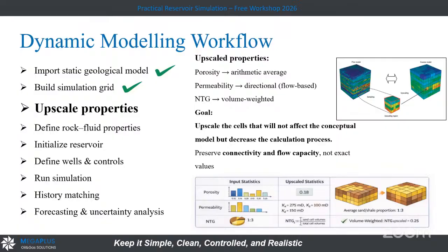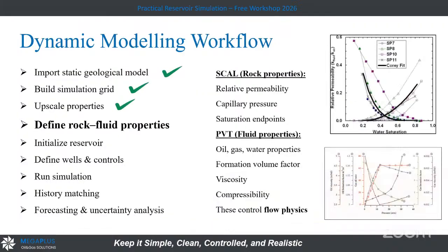So if I have a complicated or complex reservoir, as an example in the fluid, if I have a reservoir where I have to simulate a two-phase or three-phase model or a gas condensate model, you will see that a lot of composition will change with pressure. All of this adds equations. So my rule here is to minimize these equations as much as I can. So this is about the upscaling and about the rock and fluid properties.